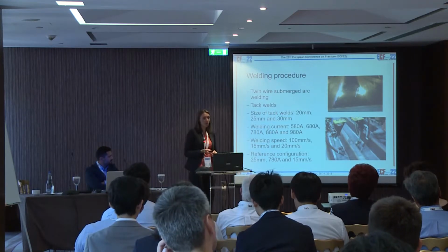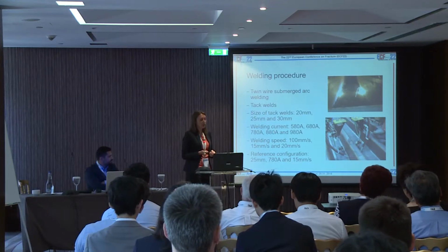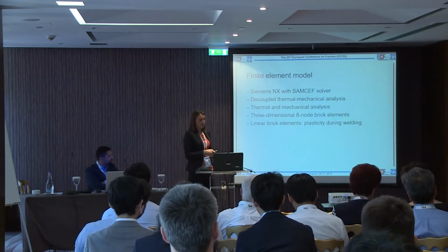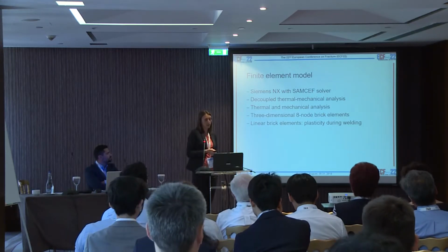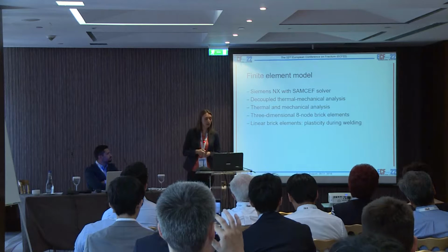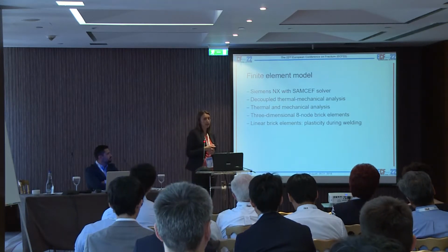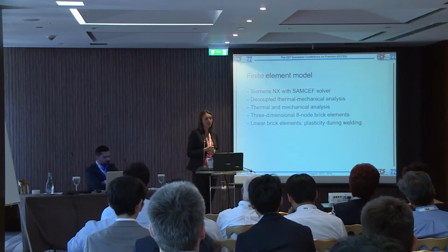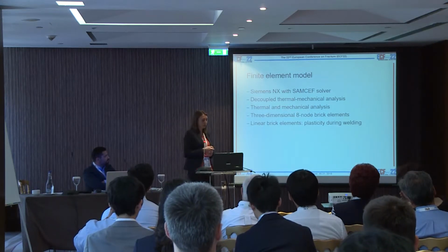For this welding procedure, we are going to look at different configurations and a variation in the size of the tack welds, the welding currents, and the welding speed. So we made a finite element model with the software Siemens NX with Samcef solver. We performed a decoupled thermal mechanical analysis. This means that the deformations are dependent on the temperature, but the temperatures are independent of deformation.